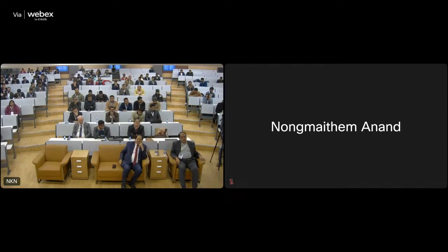Now, in this table, you will see Q original, Q modified, and then the estimation of support pressure by the equation I have shown you in my previous slide. And you will see that up to 30% reduction in ultimate support pressure in poor rock mass is expected because of the improvement in the surrounding rock mass. The important thing is that we expect the improvement up to the bolt length, right, around the tunnel opening.